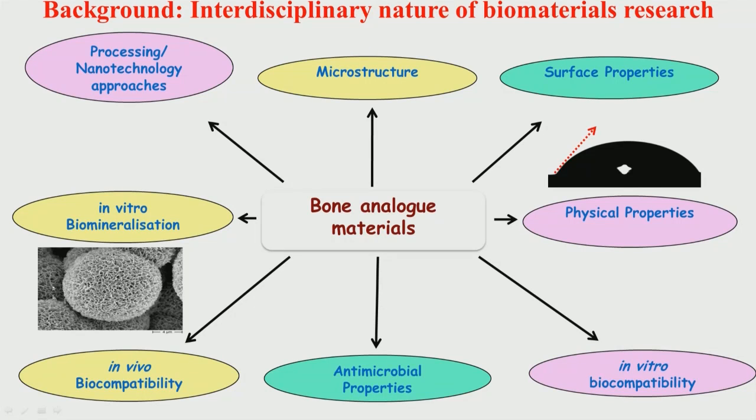However, when the same titanium material is immersed in simulated body fluid, it can induce calcium phosphate nodule formation, as shown here. These are very nicely arranged nodules, several micrometers in diameter, more or less perfectly spherical in shape. More importantly, one can notice that these nodules have a very fine pore structure, a microporous structure.